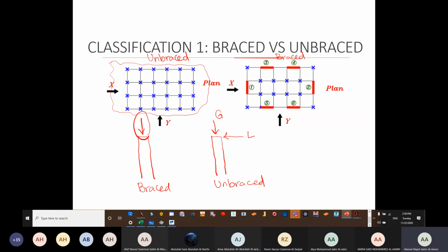Okay, so bracings. Now you can see in terms of horizontal, the column is not protected by any other member. So this column is going to move or sway. Now in order for me to protect the column from failing, you need to design it for that lateral loading.